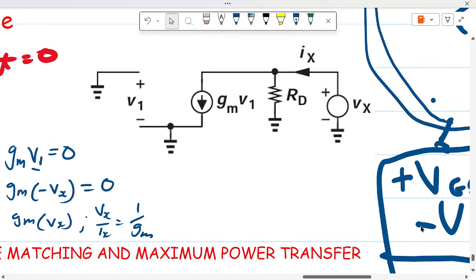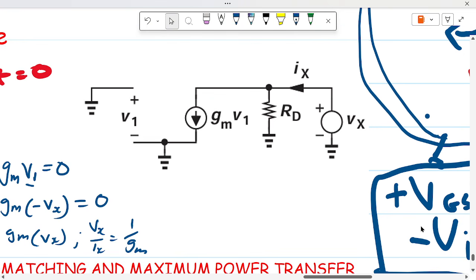For the output impedance, just as we did for the common emitter stage or the common source stage, in finding the output impedance we connect our test voltage source, this time Vx, to the output terminal, and we set the input terminal to 0.